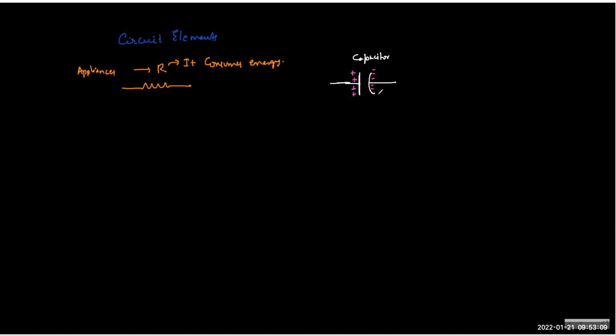In a fan, we use something called a condenser, which is the commercial or old name for a capacitor. A capacitor is a device which kind of prevents the switching, because your fan is receiving AC, so current will go this way and then go this way. If that is the case, the wings of the fan will never turn. Why? Because the current in the coil will go this way, then go this way.